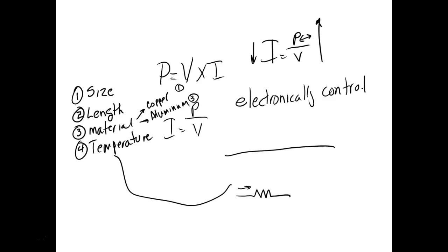So on the Amatrol lines, you can see that real easy. On the Festo lines, you'd have to go behind them. The power supply for the Festo lines is in little cubbies behind them. So power supplies, that's what's on the test. So we have two types of power supplies. We have what we call a linear power supply, which is very inefficient, but it's easy to design. It's easy to fix when they break.